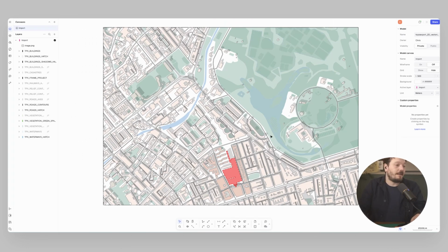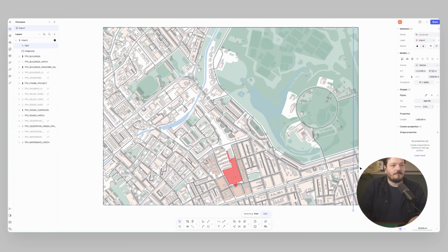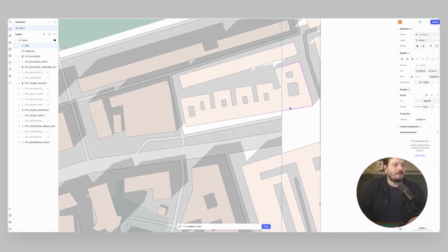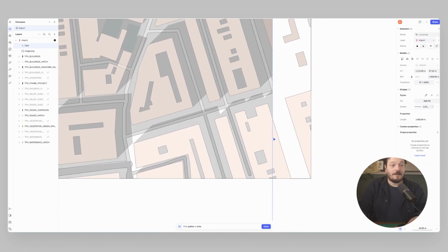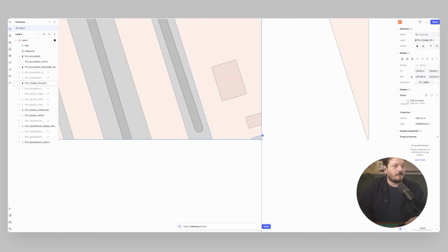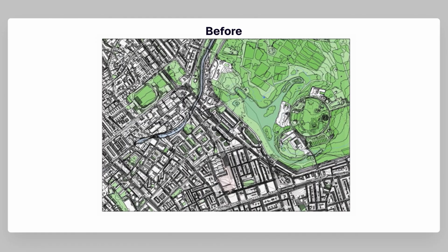If I wanted to, I could even go in and start cropping the edges of these elements. So for example, say I wanted to bring this boundary in, I could just select this line and press trim, and then that allows me to knock back these elements with their fill. You can see the shapes updating, the fills updating based on this edge. Trim again, and I can just trim my boundary line. Here we go. Clean that up. Perfect.